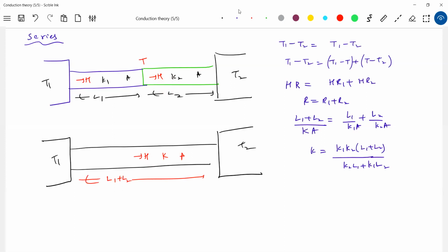It has wide applications, and for us, they are simple numericals here. Okay, what is this K? The equivalent thermal conductivity. So when two rods are in series, what is the effective resistance? R1 plus R2. Thermal resistance, not electrical resistance here, thermal resistance.